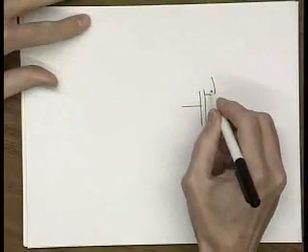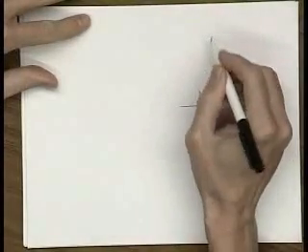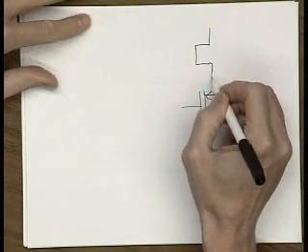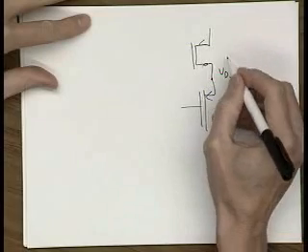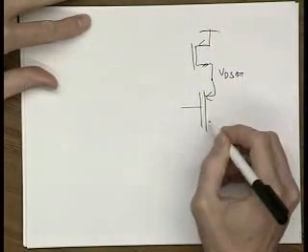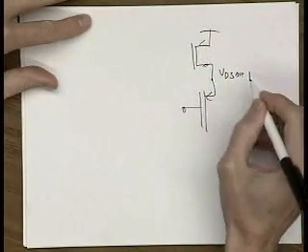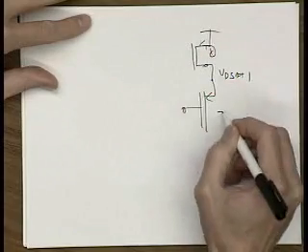If some transistor needs to be biased at, say, some sort of high swing arrangement, then this needs to be at a VD sat of this transistor. And that means this voltage here is VD sat 1. Let's say this is transistor 1, this is transistor 2.